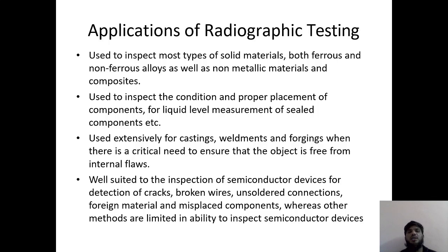And what are the applications? If you see, it can be used to inspect most of the solid metals, both ferrous and non-ferrous. It can be used to inspect the conditions and proper placement of components, for liquid measurement, and for inspecting castings, weldments, everything. You can see the defects and cracks, broken wires, everything can be done by using radiography.